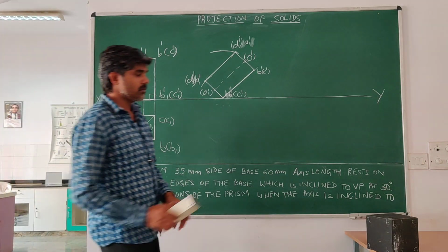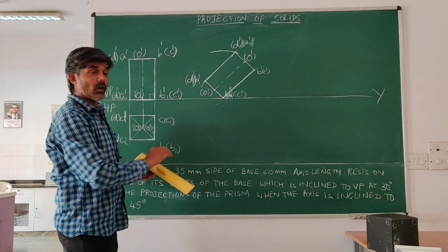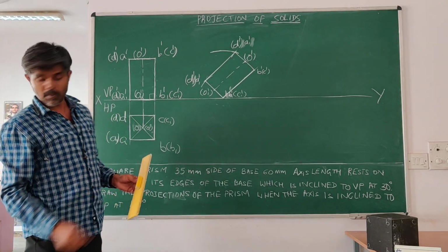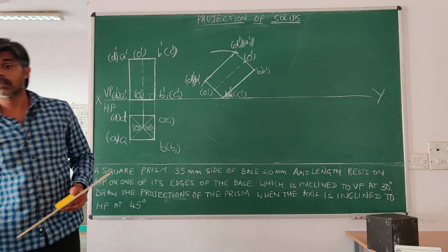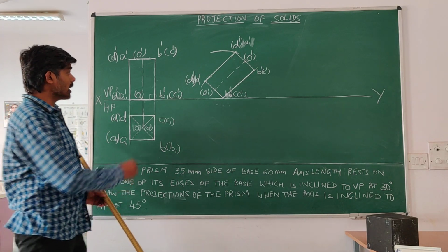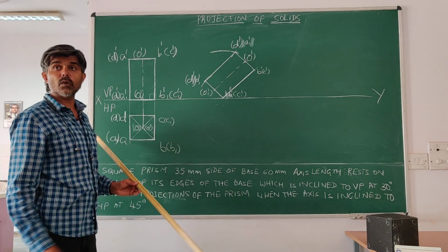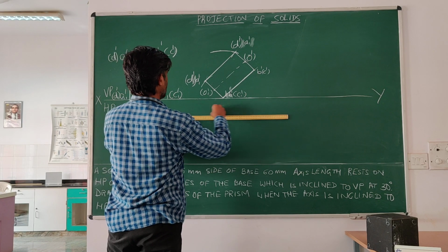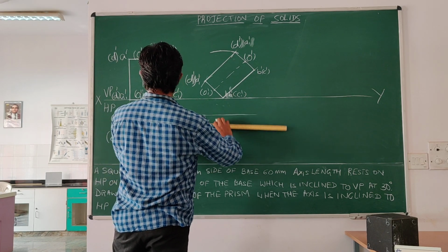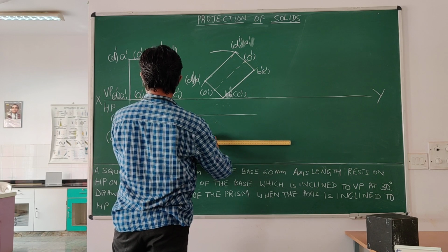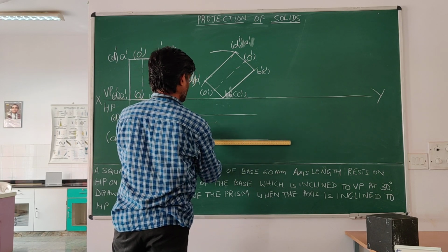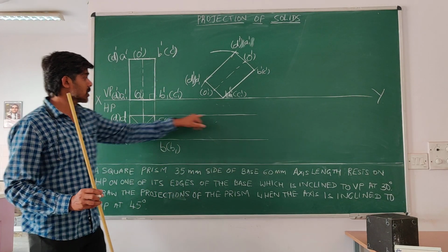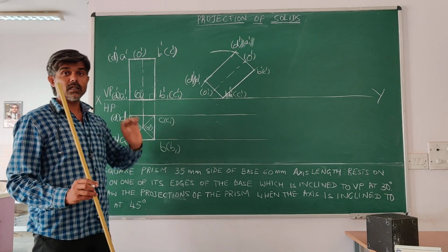To get that, we will be drawing the horizontal projection lines and vertical projection lines. So let me draw those things. Okay. Now to get the top view, we will have the horizontal and vertical projection lines. Let me draw the horizontal projection lines. So these are the horizontal projection lines. Next, vertical projection lines. Remember, these projection lines should be thin and light.